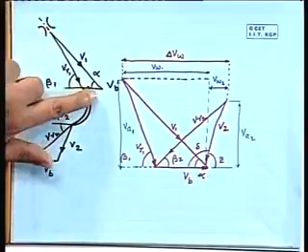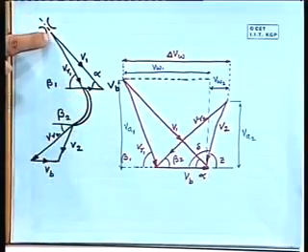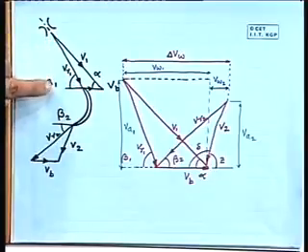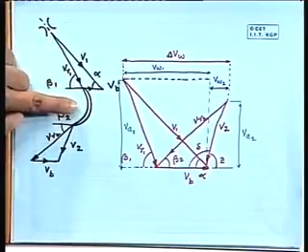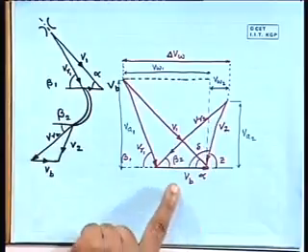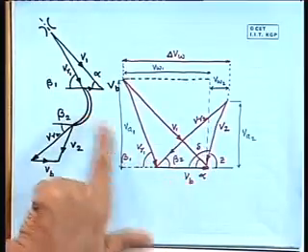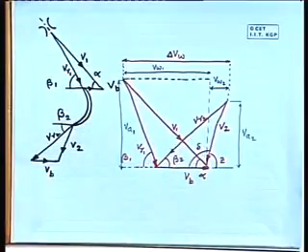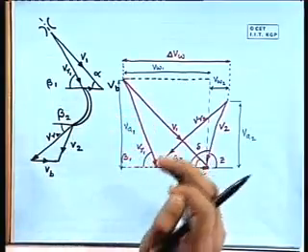Now, quite a few things can be selected, like one can select the nozzle angle, and one can select the tangential component of velocity for the blade, which is Vb. Because we know that it is a function of rotational speed RPM and the diameter of the turbine.